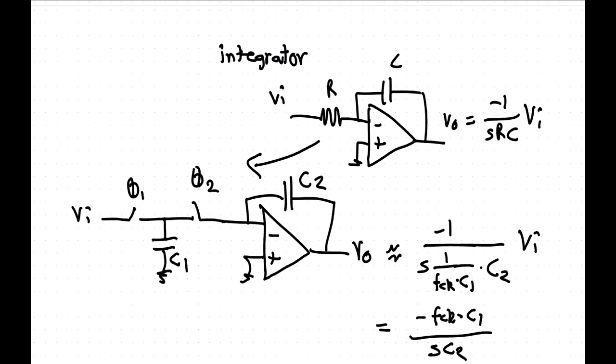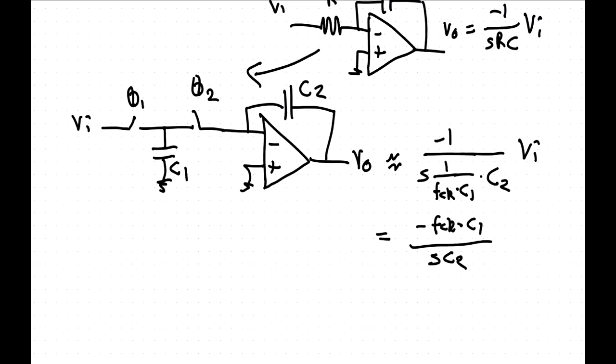However, if we look at what happens in the switch capacitor filter, then the filter pole location depends on the ratio of two capacitors. And if that has an absolute variation of plus minus 20%, that probably doesn't matter because the ratio is going to be accurate. We have good matching between the capacitors.